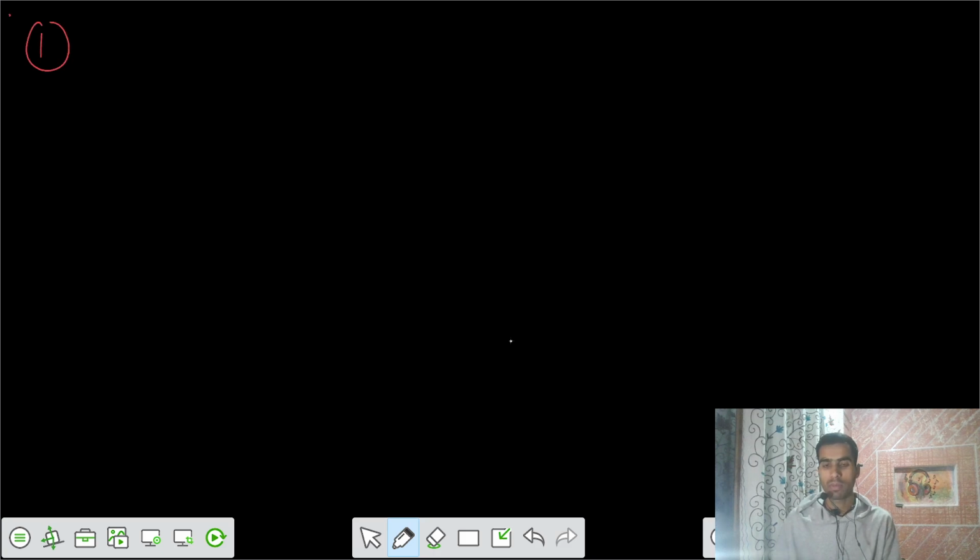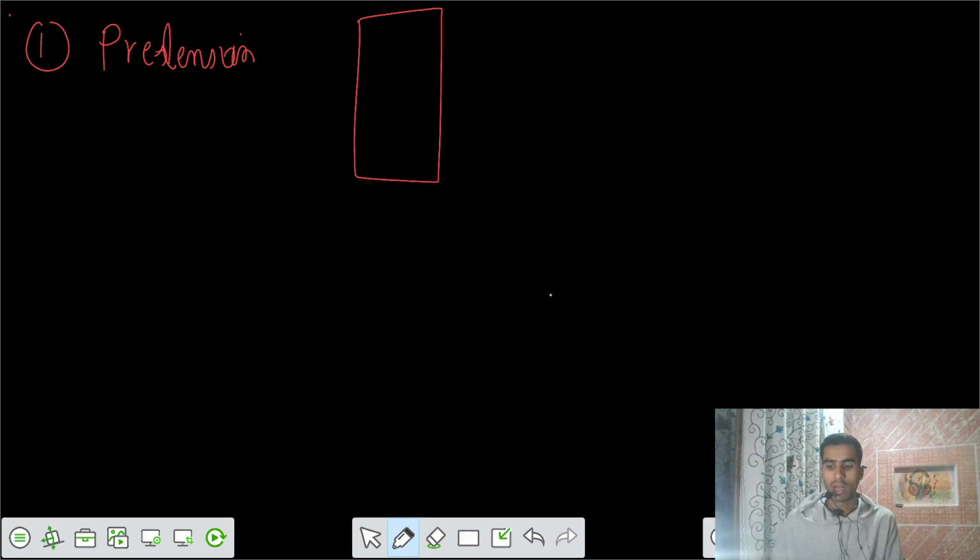Let's take the first problem that we have, for the elastic shortening of the concrete. That is the loss of prestress because of elastic shortening. We have a pretension beam of 100 cross 300, and we have a straight wire. Wire is straight, that means we don't have to calculate FC average. We have to calculate FC directly.